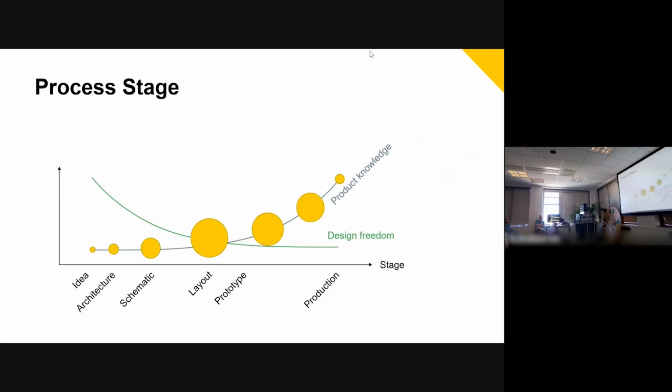What I would like to suggest is to have proportional doses of attention, in this case for signal integrity, along the way. So for example, in the idea phase, it's perfectly fine if just your team watches a 30-minute awareness video on signal integrity and asks themselves the question, are we concerned? That's enough. A little bit later, when the architecture becomes more clear, you can do a 48-hour quick scan, with some numbers to discern where the big risks lie.